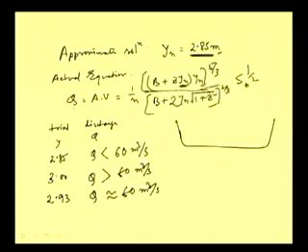And now, what is the advantage if we go by this approximate formula? Suppose we are using this value 2.85, which is basically the approximate formula value, and from here we are starting. So with very limited iteration, we are arriving at a correct value. In field condition, if we need some approximate idea, we can use this advantage, and then we can go for trial and error to see what the actual value of yn should be. So that way we are calculating these things.